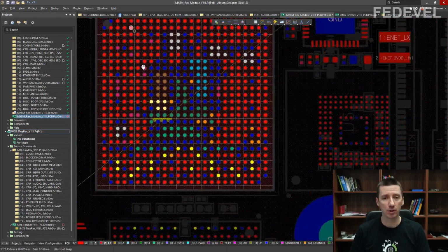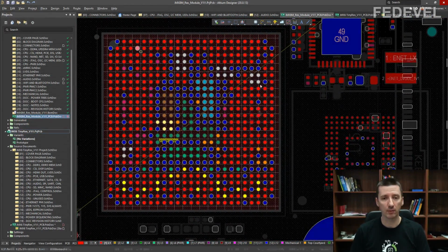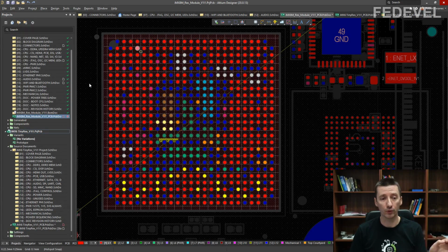Now, because Mike mentioned they will be doing this in two different drilling processes, I wanted to know if they need two different drill files. I wanted to ask this because usually these CAD systems like Altium generate only one drill file. I wasn't sure how I would generate the second drill file.